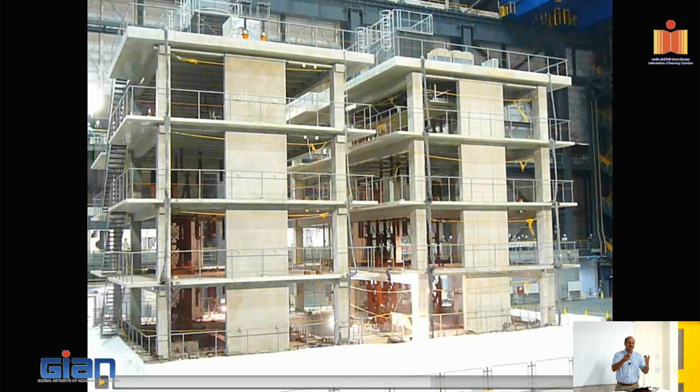I know there was a concern about sliding, but this wall was not sliding, and you could see after a significant amount of testing, there's no damage to the entire structure. And the post-tensioning was designed to remain elastic even after subjecting to all these earthquake motions.